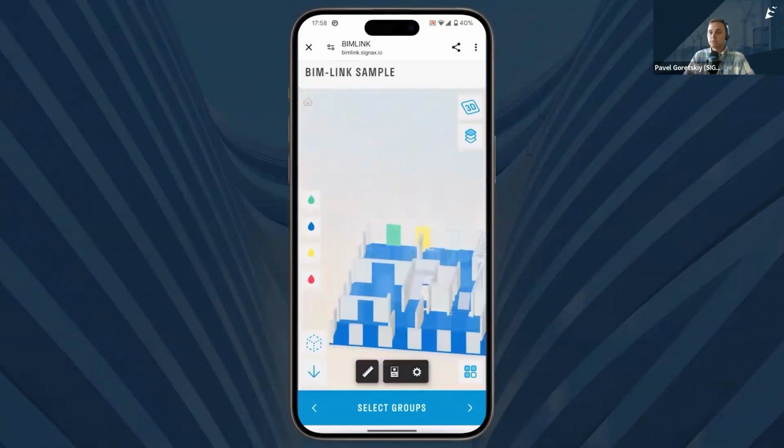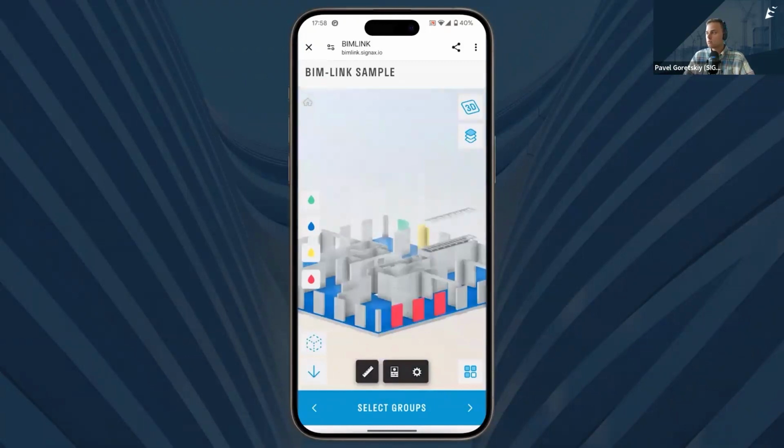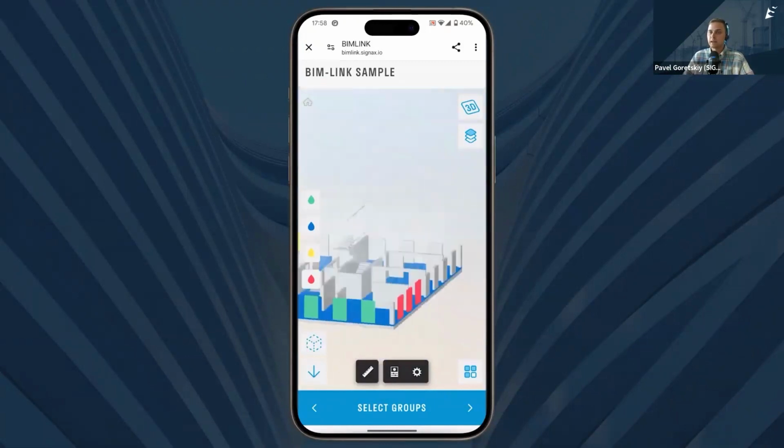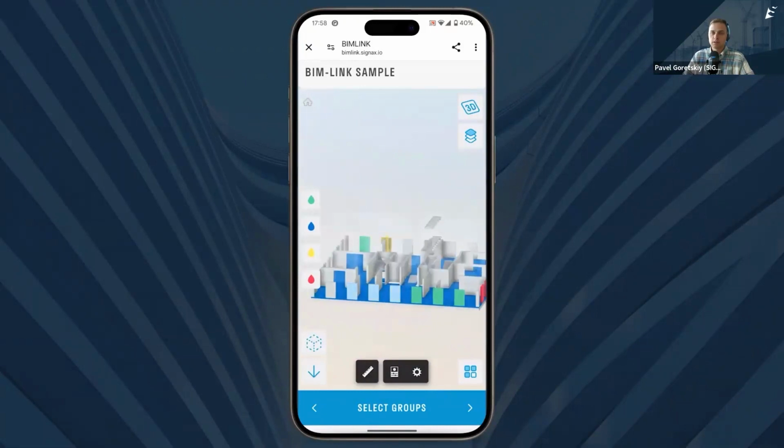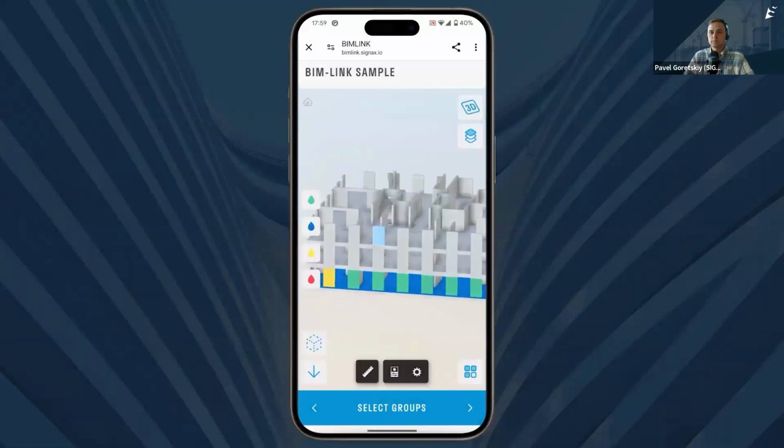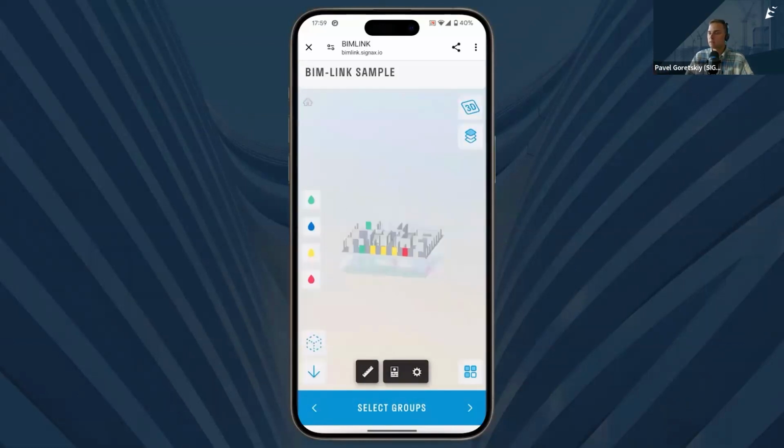So then, the workflow is pretty much the same. You select elements, sync colors, and later you download JSON file. So it could help in the commissioning stage of your project. So you go to the commission on site, you see these works are verified, QA/QC approved, green color; have some issues, yellow color, not approved; you have to fix everything, like red color.